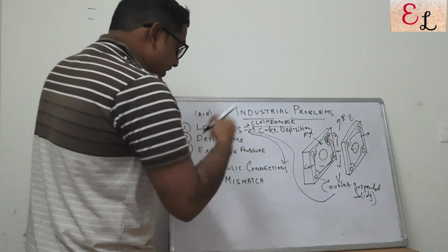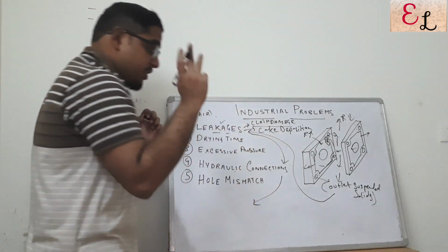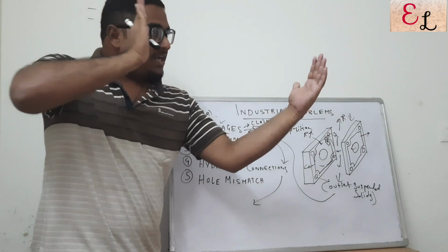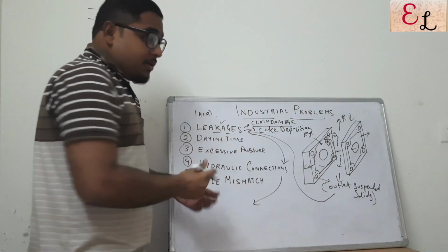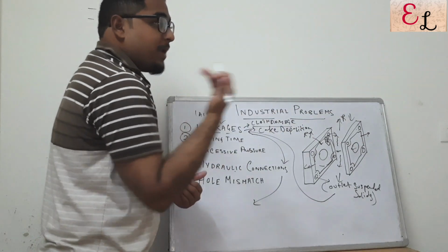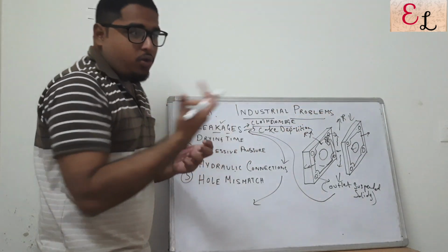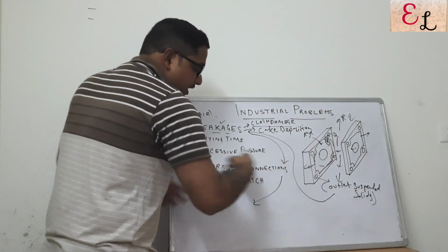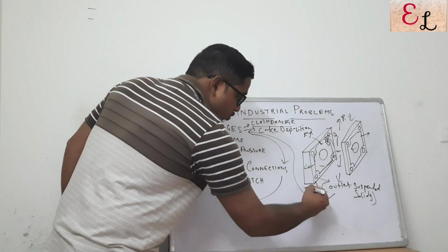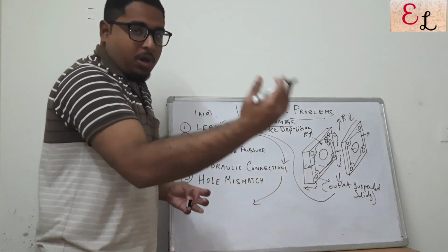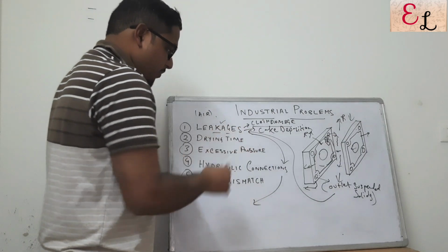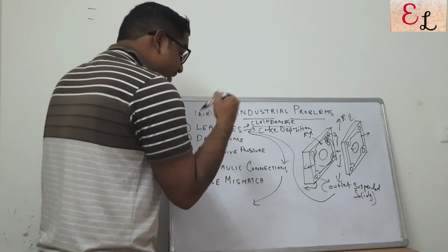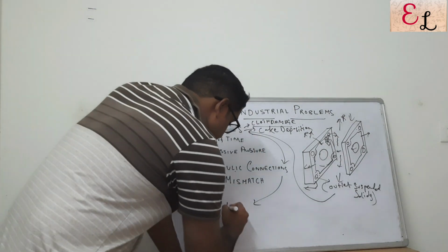Now let us discuss simultaneously the problem of hydraulic connections. Hydraulic connections are primarily linked with the pressing of the filter press, that is, the plates stacked together under high pressure, and the drip tray opening and closing, and the shifter plates to pull out the plates one by one so that they can be cleaned and set apart. This system is supported by hydraulic connections, and hydraulic connections are basically pistons